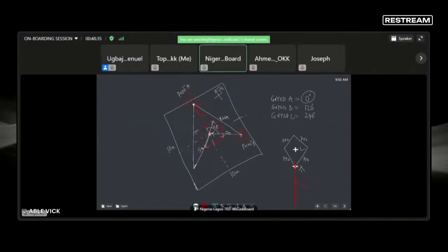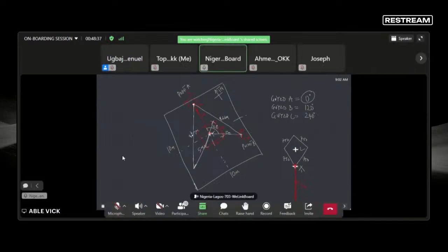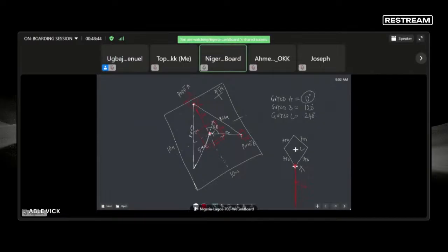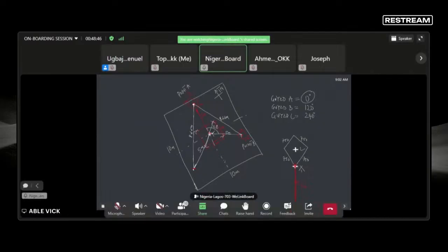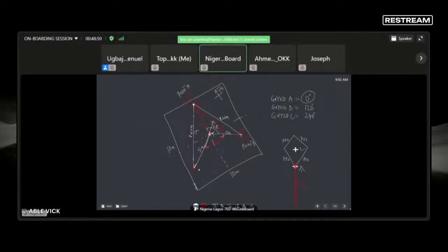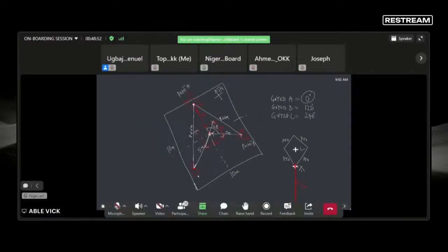Having 5 meters here. Having 8.66 meters here. Wherever the two tapes intersect is your 120 degrees, and that is the middle of the base plate, not the edge. So from that middle, you can now set out your base plate.